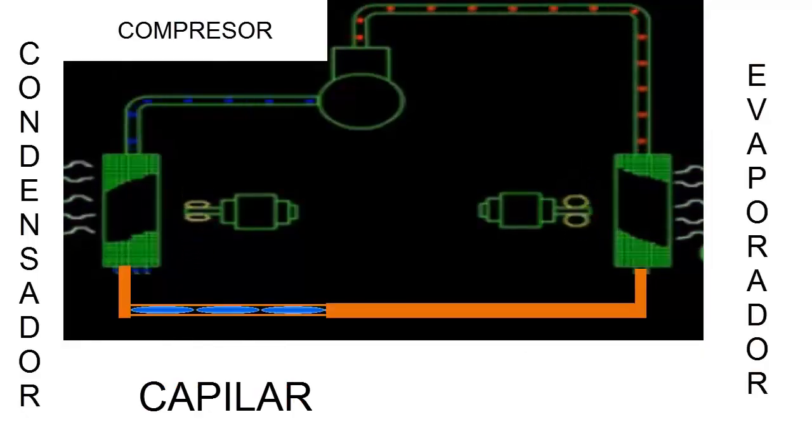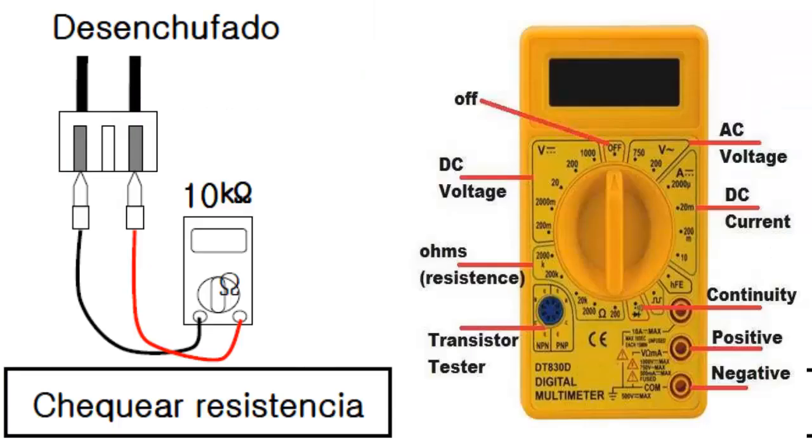In case the value supplied by the manufacturer is not met, we must touch the sensor, rub it to add heat, and verify if, when increasing the temperature, the resistance of the sensor drops.